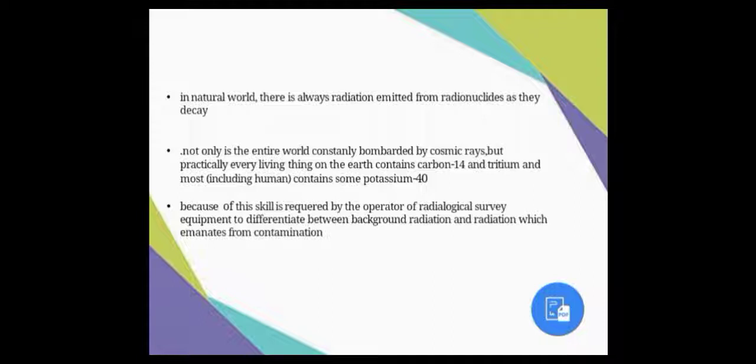A particular problem is the encounter with naturally generated radon gas, which can affect instruments that are set to detect contamination close to normal background levels and can cause false alarms. Skill is required by the operator of radiological survey equipment to differentiate between background radiation and the radiation which emanates from the contamination.